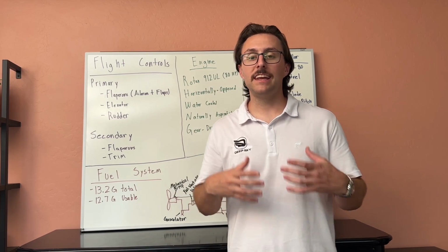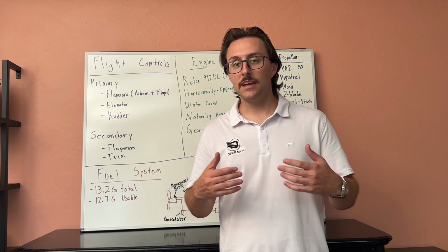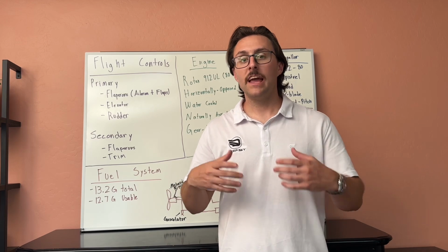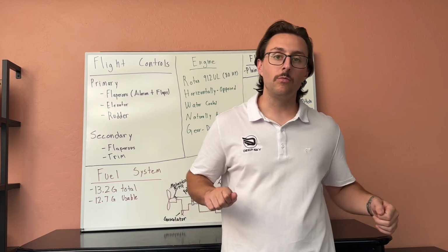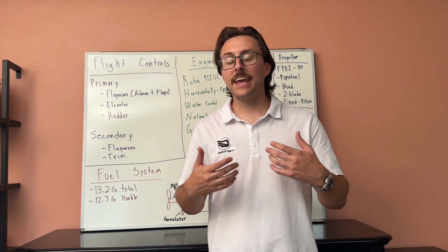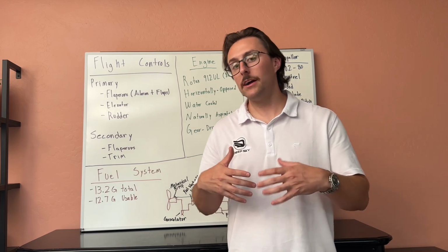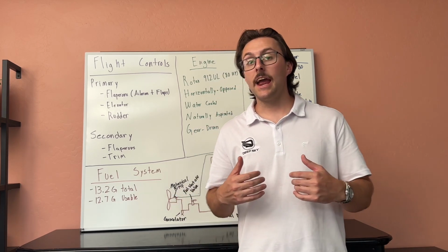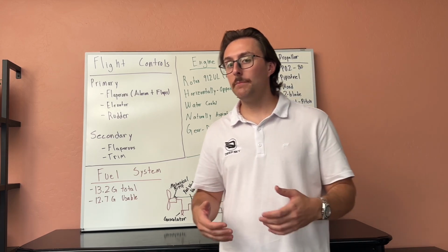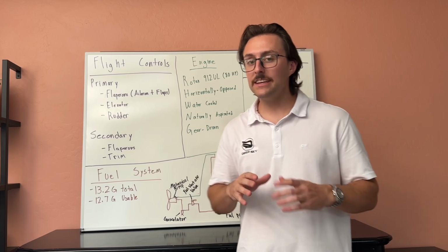The trim is an electronically motor-driven trim. So what does that mean for us? That means that we just have a little thing that we flick back and forth, as compared to a more traditional aircraft where it's a wheel that they can actually move back and forth. And that's typically cable driven. So our flaps are actually mechanically driven by rods, and the trim is driven by a motor going back up to the primary flight controls, which on our aircraft are slightly different than the traditional ones.